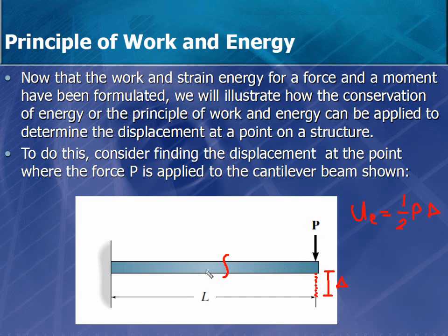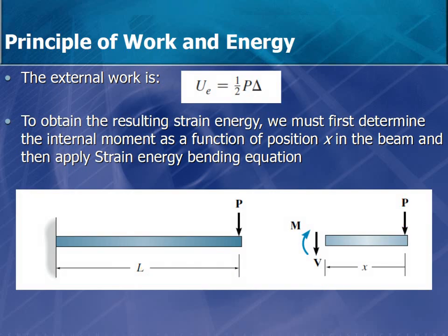So the moment is the internal strain within this beam, because the load I have here creates internal moment. Anywhere that you take, the moment is going to change. Why? Because we said moment depends on x. So we're going to use integration in order to find the internal energy. Well, let's say that this is the external work. We talked about it. So in order to find it, we're going to take a section here, and we can find the moment with respect to x.